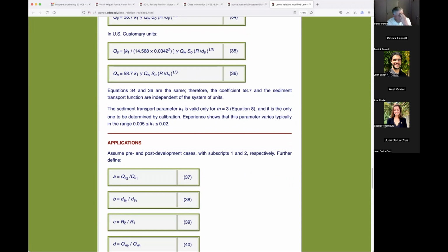Because people that have studied sediment transport, like Simons and many others, have realized that there's some relationship between the quantity of sediment transport and the so-called stream power, where the stream power is tau times velocity. And I already talked about this when we talked about Simons's paper. Simons really emphasized and expounded on the concept of stream power.